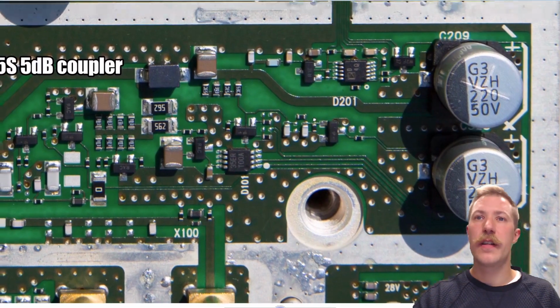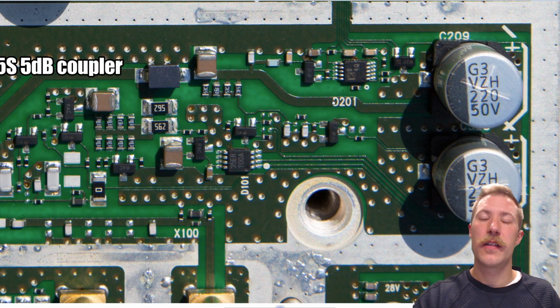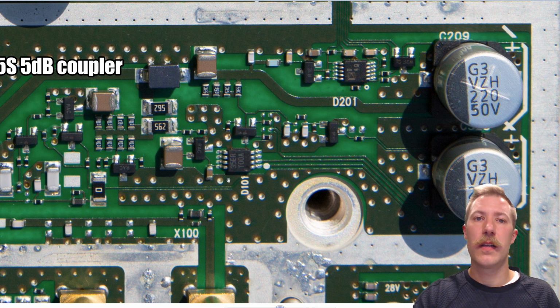Now he also reverse engineered that this is actually a digital potentiometer, which is an Analog Devices I2C component, along with an LM75A digital temperature gauge, which is also controlled by an I2C bus. And he wrote an Arduino library to control these two ICs, so you could control the amplifier without the native environment. Very cool stuff, and I will ask him to post his results on the High Voltage forum in this post for this video, so you can all see the results if you're interested in those as well.